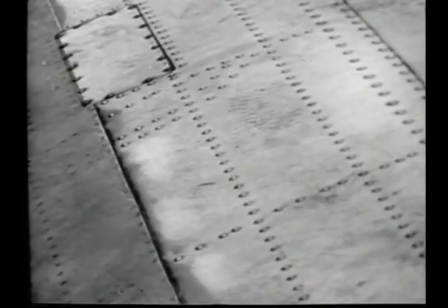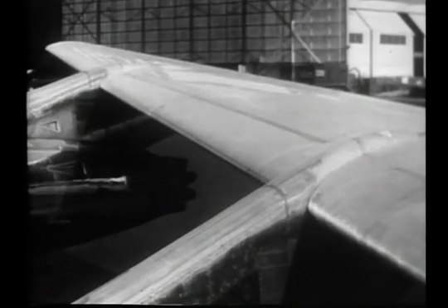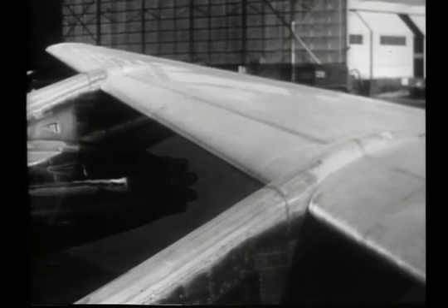The location at which transition occurs depends both upon the nature of the disturbances to the laminar boundary layer and its stability. The designer has learned to control some of these factors. Disturbances arising from rough surfaces can be reduced. Other disturbances, such as noise, vibration, or airstream turbulence, can sometimes be avoided or isolated.